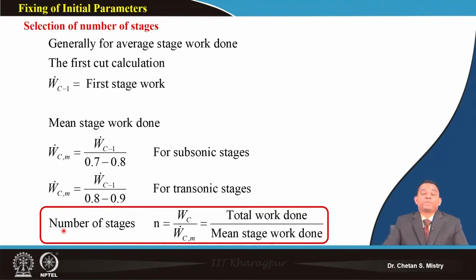Let me say the HP compressor is the most important. If you recall, in the last lectures we discussed that the HP compressor is the heart of the engine. A few percent loss in efficiency reflects as a great reduction in fuel economy. At the same time, it may be subjected to stall formation or engine failure because of surge. That's why people are very careful when designing the HP compressor. So let's discuss how we decide the number of stages.